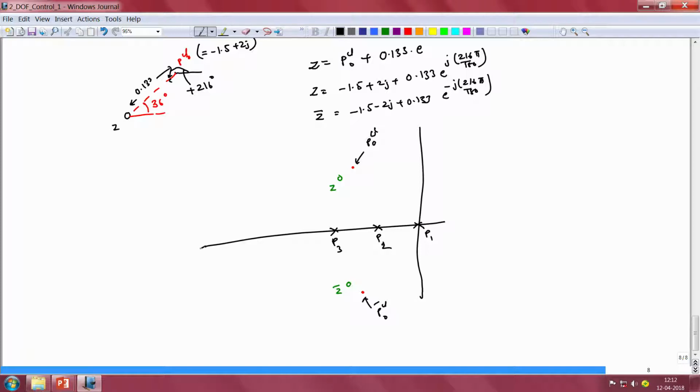Now we also have 2 far away poles, namely P4 and P5. We have not yet fixed the positions of these poles. It turns out that it is not an arbitrary choice, and there is some caution that needs to be exercised while choosing the positions of P4 and P5. So the second step in the design is to determine where we can place P4 and P5.